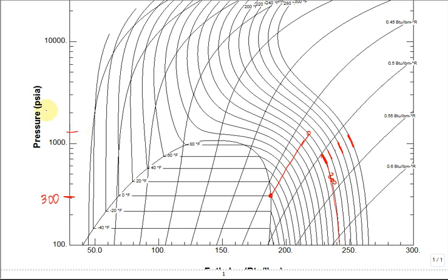It's up in this ballpark. This is 2,000. You have to read this diagram, but it looks like it's what? 1,400 psi? And if you then cool it, it'll cool until you get to a temperature. It can't cool any below, what did we say, 140? It can't cool below 140. It has to reject heat to the outside.